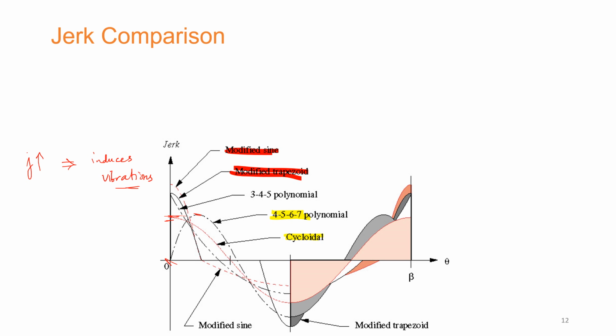So with this jerk comparison giving you some deeper insights, you realize that a profile performing really well on the basis of acceleration may not behave very well in case of jerk comparison. So you need to strike a balance between the selected kinematic parameters to make the final decision.